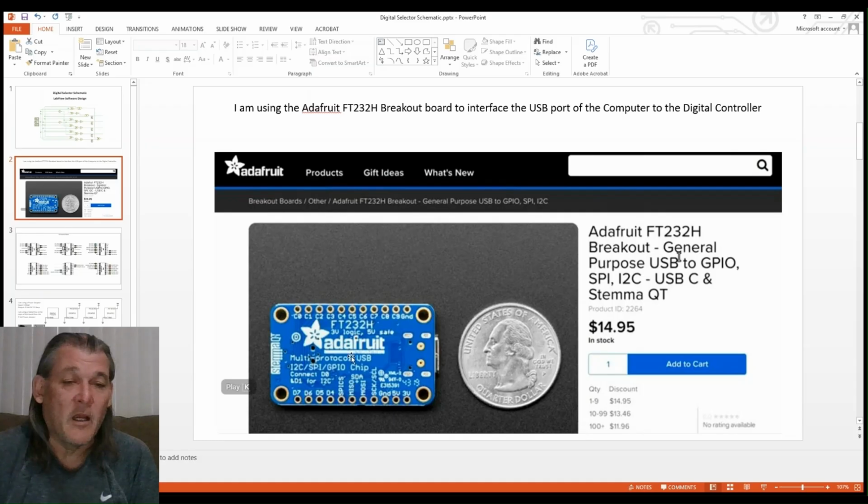These are the bits that I'm using, C0 through C7, and I'm using the ground pin. I'm not using any of these other pins. Do not use the 5 volt and the 3 volt to supply power to this board. Do not supply power to this board. That is done by the USB interface, by this connection right here. Adafruit gives a warning about using that 5 volt and that 3 volt. I would not use those.